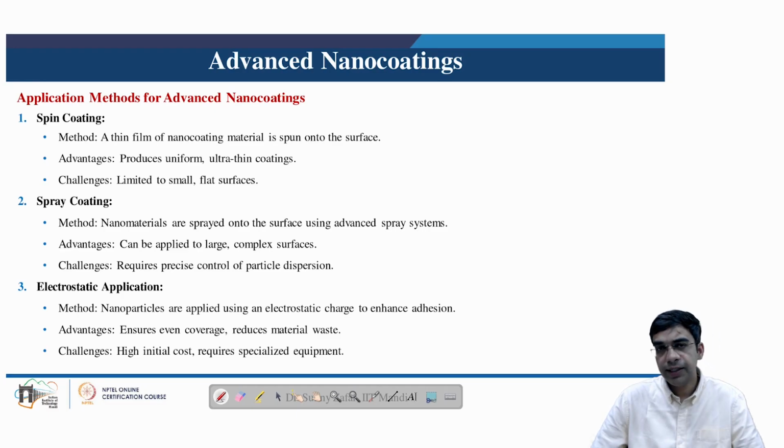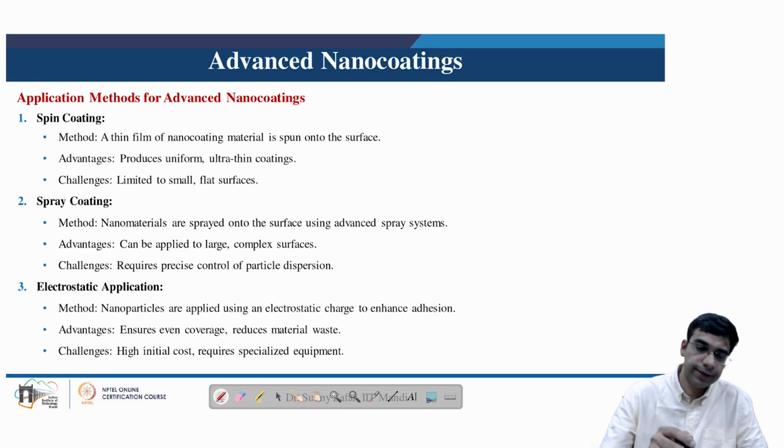The third method is the electrostatic application. In this method, the nanoparticles are applied using an electrostatic charge to enhance adhesion. The advantages of electrostatic application include even coverage and reduced material wastage. The challenges of electrostatic application are high initial cost, which requires specialized equipment.